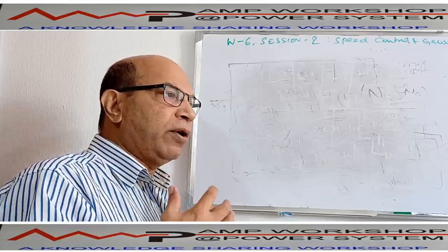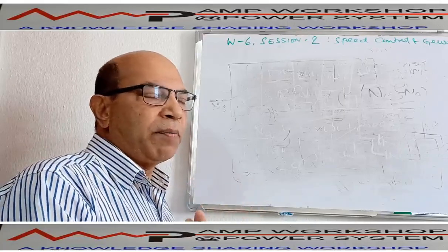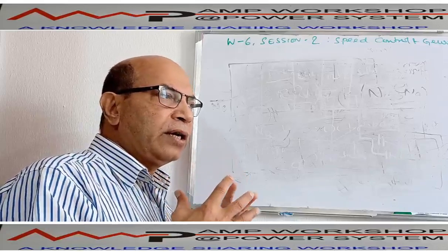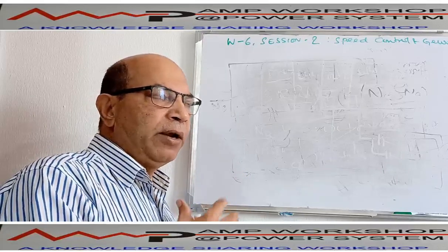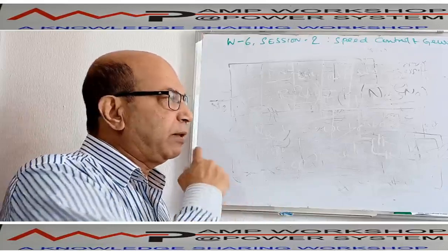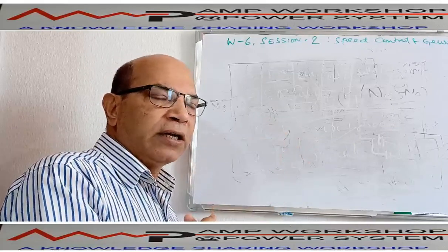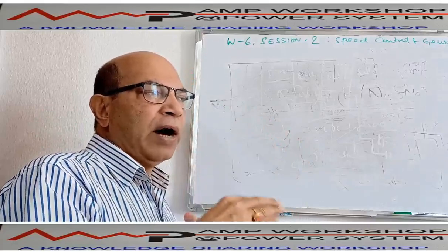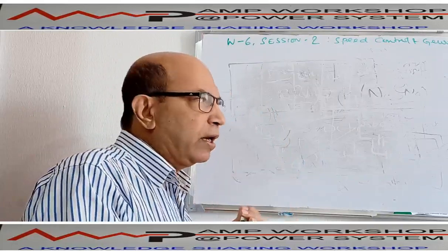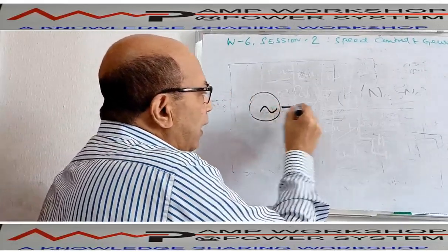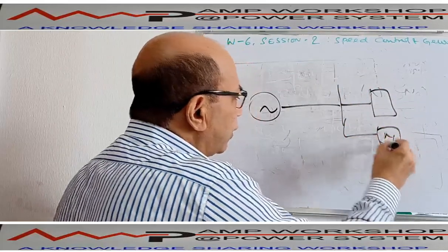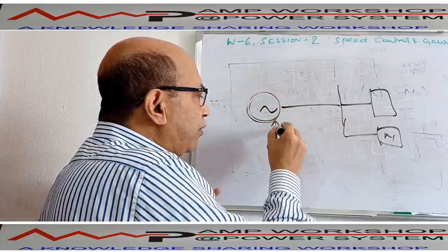Now, in case of the governor, as it is speed control, how is the operating mechanism working here? The moment the governor understands there is a change of speed, immediately it will give a signal to compensate that speed. As per this equation, the governor will give the final signal to the actuator to open the valve. The valve will open, fuel will go immediately, and it will change the frequency. This is for the single machine we are talking about. Suppose a single machine is running and carrying load, and suddenly a new load has come up. Immediately the generator speed or frequency will drop down.